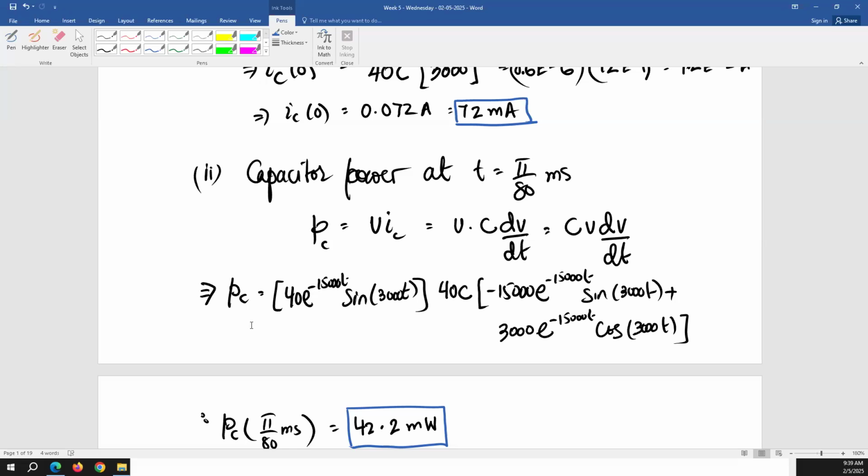Those are happening in a very short period of time, but they're making a very large change. Lightning, as I said, is one of the very common examples of this. If your voltage is changing in an instant of time, then the rate of change of that is going to be infinity, and that current is just not possible. It's going to burn everything, basically. So even mathematically, you can see that it's not possible for the voltage to change instantaneously across a capacitor. Otherwise, the current passing through the capacitor is going to be infinite.